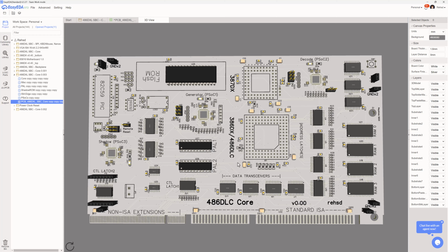Also, what I could do is on this card, for at least the core card, and maybe this other card that would have, for example, the flash ROM functionality, I could maybe, instead of the ISA slot 2, just go with maybe even a single just proprietary connector that's a PCI that gives me just the signals I need to get to that other card, or a pair of these PCIs that really give me all the signals I need into some form of a backplane bus that might have ISA connectors on it also, but maybe for some of these core cards, it doesn't really matter what I use for a connector.